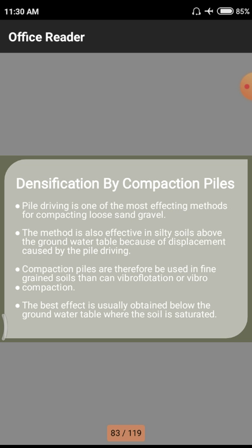Normally, bores and augers for small-scale structures are operated by manpower. A man pours some water on a particular place and uses an auger, rotating it continuously so that the auger penetrates into the earth and creates a space. In that space you can place the foundations and others.